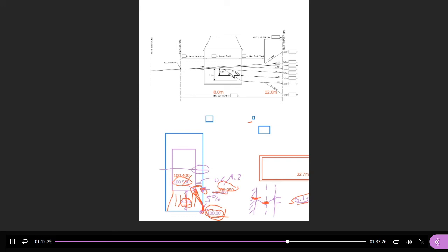Negative. Yeah, it's going to be negative 1.94. So from the front of the lot, you're going to be almost 2 meters below at the back of the house. Then from there, I want a full usable backyard. So go down to the back at 3%. And what number do we get there? Negative 2.32. Very good. So that would be the elevation.